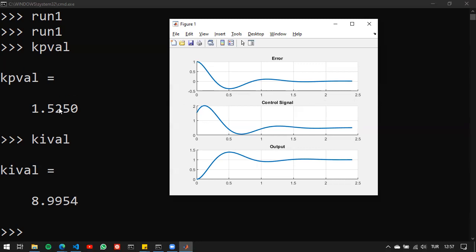Therefore, it's kind of a P-type controller at t equals 0. Of course, if we pass one sample, we see that it is growing here because we have 1.66 and the error is going down. So Kp times 1 should give us only 1.52, whereas the control signal is increasing because we have this integrator and it is giving an output other than 0.